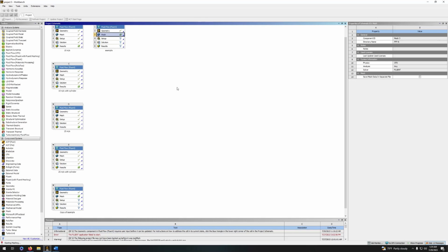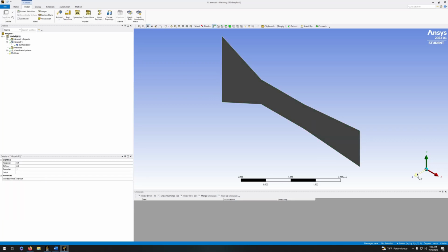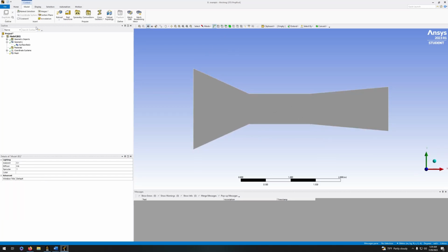First, we're going to have to name all of the walls. Okay, let's wait for it to come up. Okay, so we've got this surface here. Now let's go ahead and name everything. So go to edge select, select this and call it velocity inlet. Okay, and we'll select all the outer walls by holding control. Should be 6 of them, and you can tell by looking down here. Press N and then just call them walls. Okay, now we're going to select the outer part, call this outlet.